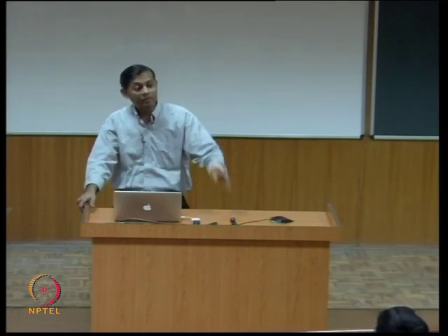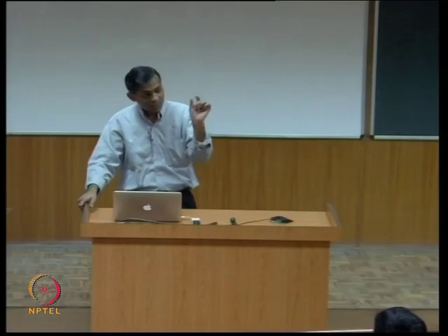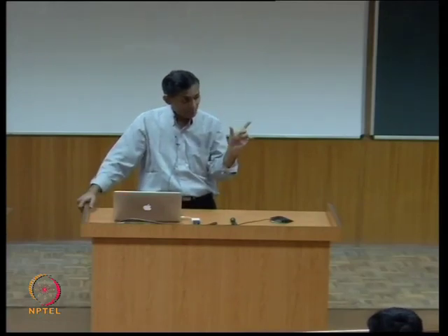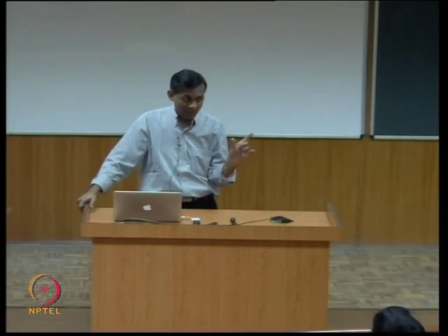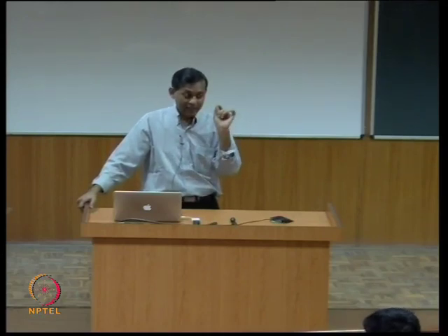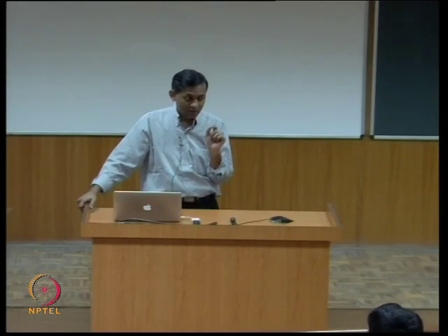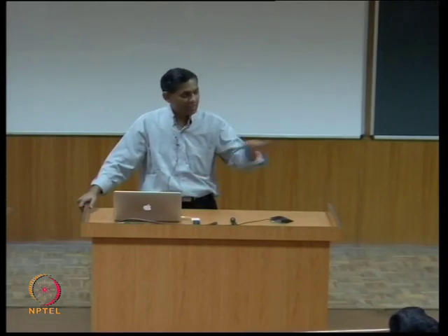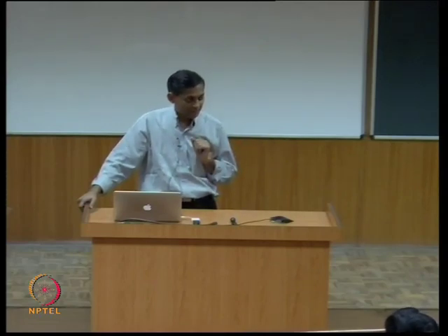What I want to say is that each SM has its own ALUs, and each SIMD unit on the SM, there are 16 of them, has its own ALU. In a given clock cycle, on one of those 16 SIMD units, you can execute one instruction for 16 threads.